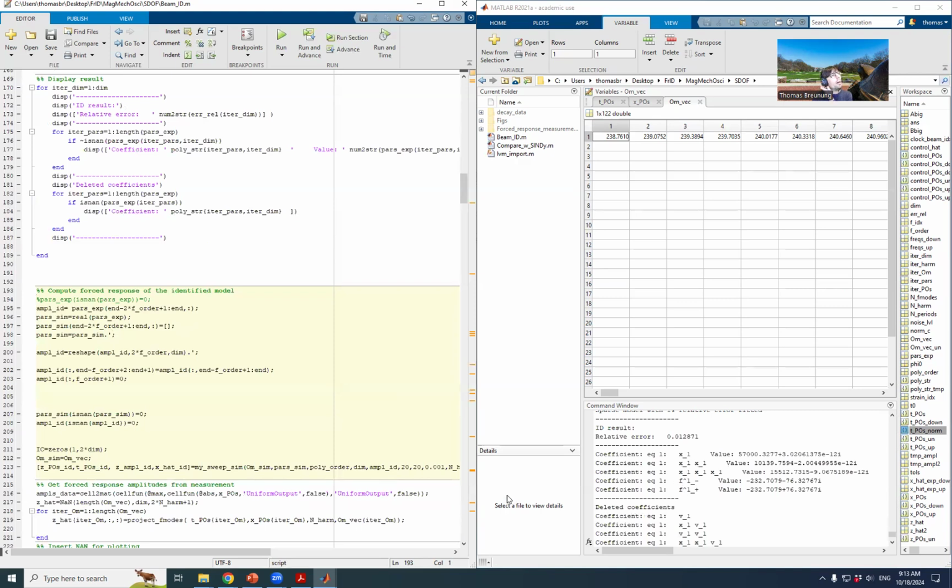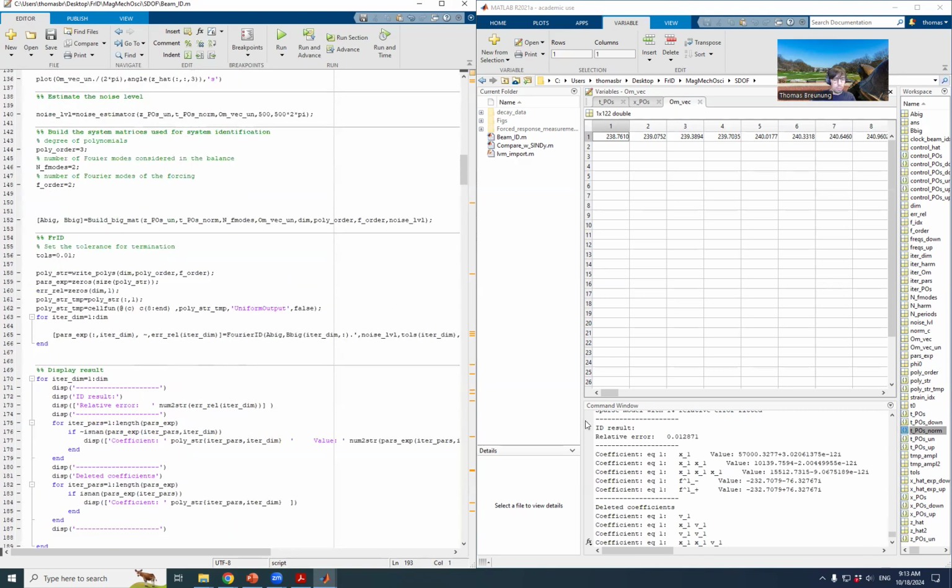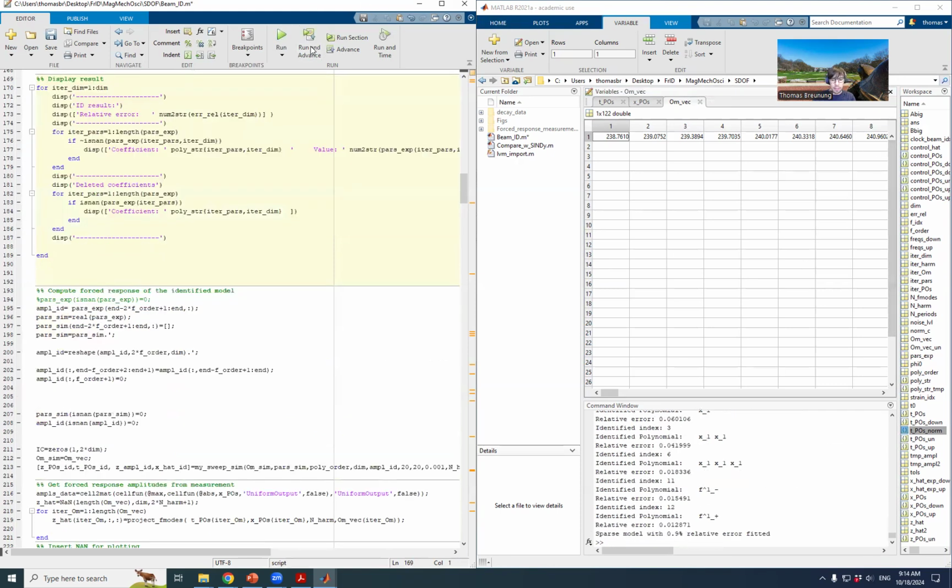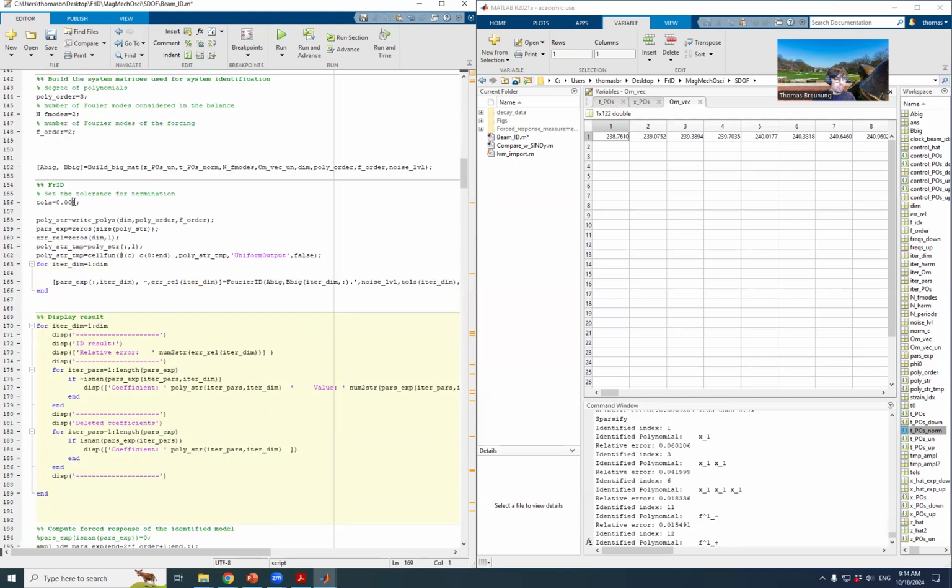In reality, in nonlinear structural dynamics, we suspect some damping, so we could already see that this model will not be performing too well. It will still not be bad, I think, for certain applications. So in this case, this already tells us maybe we should increase the tolerance a little more. We increase the tolerance to, let's say, 0.98. Let's do that real quick. Yes, and then we can see now that the nonlinear damping is included in the fitting.